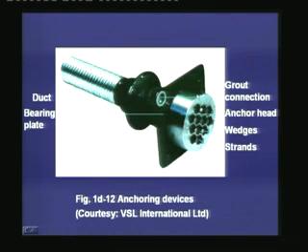In this photograph, you can see the assembled unit of the anchorage block. At the end, we can see the anchor head, which can accommodate several wedges for the strands. There can be a hole in the bearing plate through which the grout can be passed. Then we have the trumpet shaped conduit, finally which is attached to the duct which is placed inside the concrete.